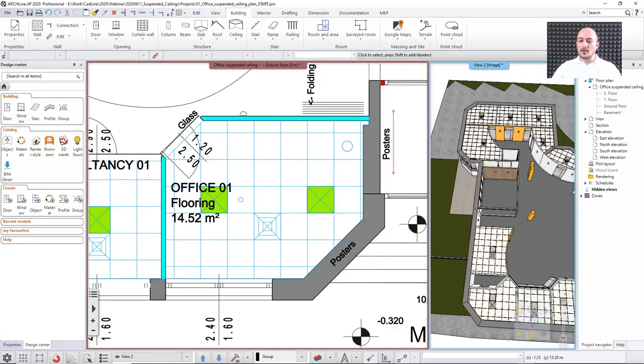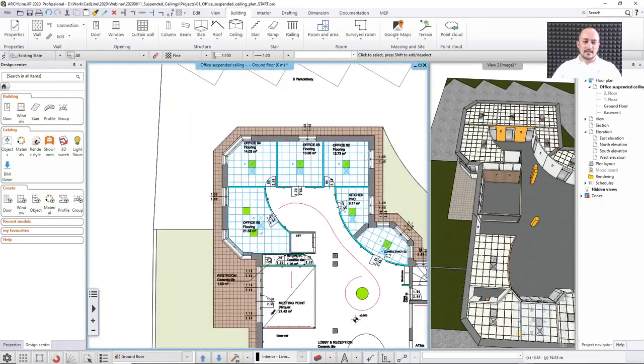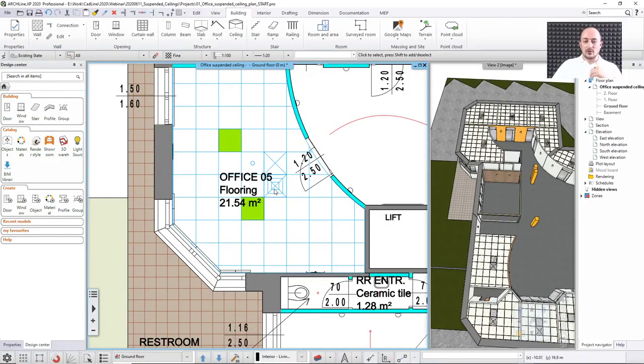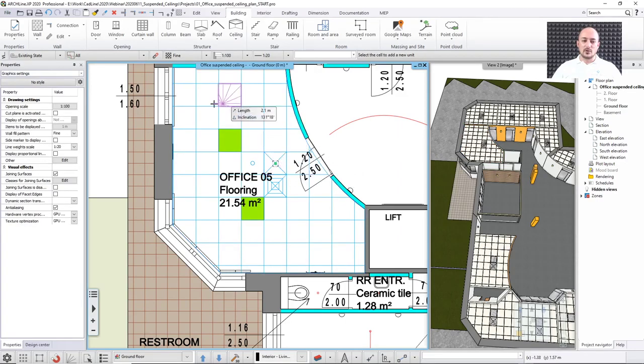Now let's just do one other change with the grid ceiling, and then we will move on and discuss the plain ceilings. Here I mentioned that I will show you another case where you will understand how you can manually reorganize the units in the 2D shape, and that comes with the markers. When you select this, and let me just remove this here, and you click on any of those markers, like for example, I'm clicking on the lamp here, you have these unit options: move, copy, delete. I would like to move this from this location to another grid point, for example, to here.